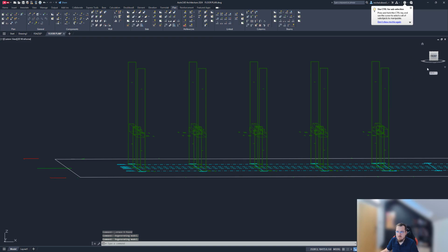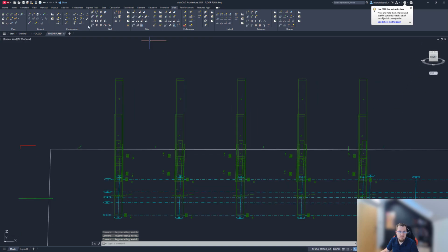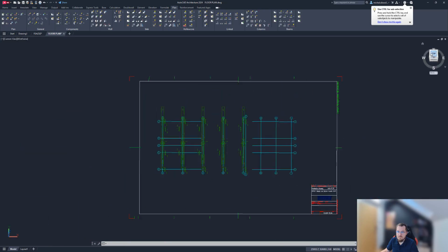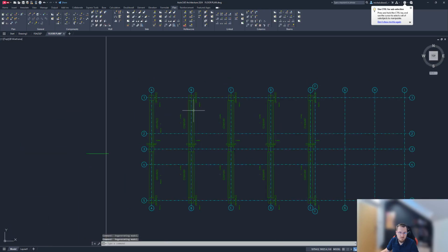And it's as simple as using the other option that we have, draw corbel from element. What will happen is Impact will recognize which elements are columns, which elements are beams, and it will try to place the corbels accordingly, according to that recognition.